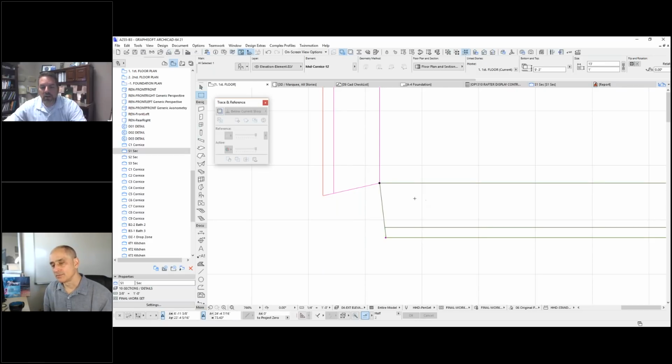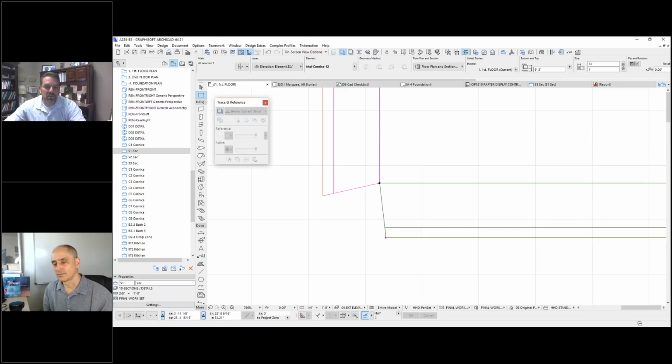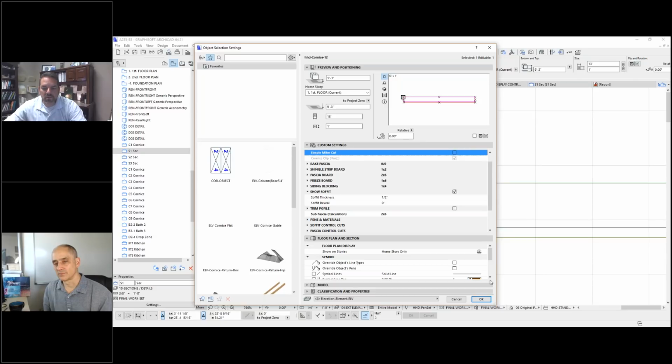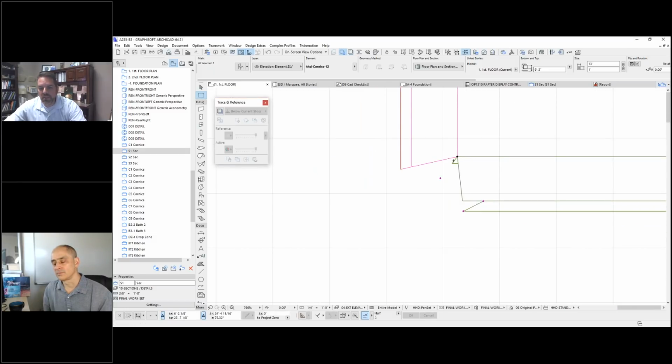Now, if they're irregular overhangs, if I went into this object and specified a complex miter, it's under simple miter, but if I went to a complex miter, I can actually do each one to mend that outside or inside corner if they're two different overhang sizes.